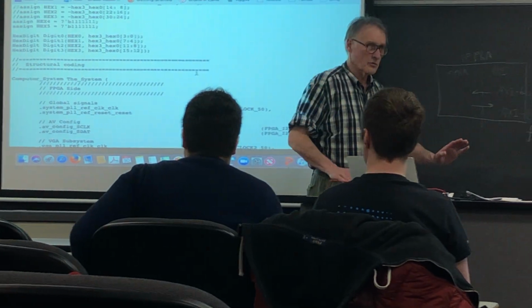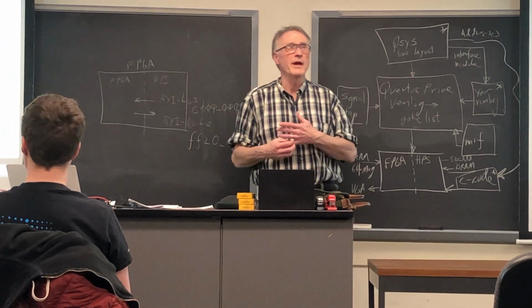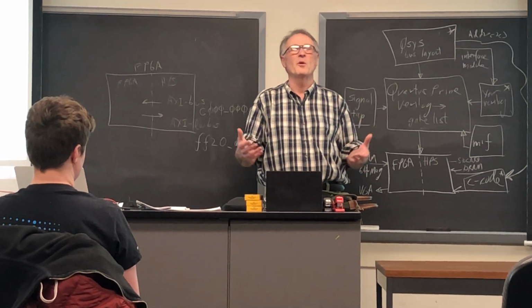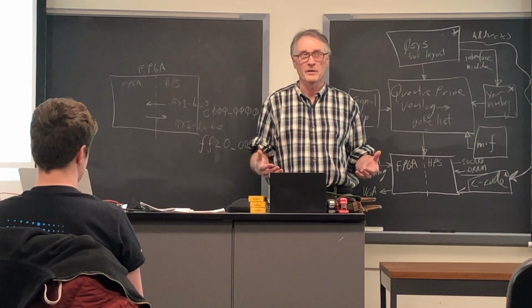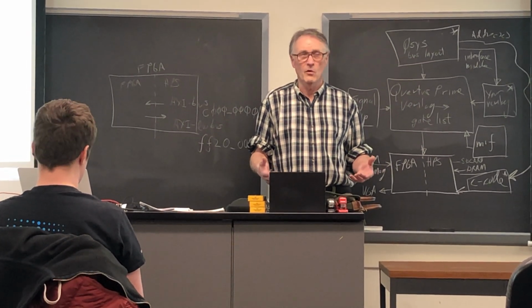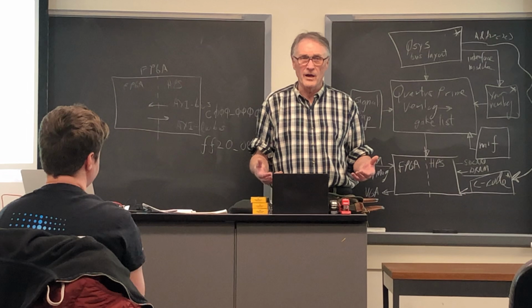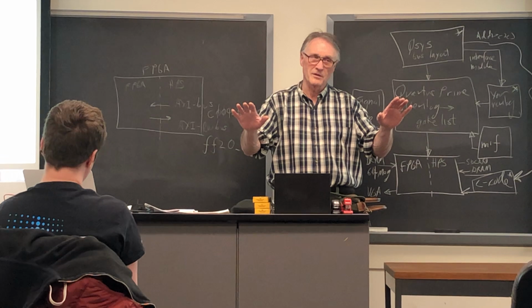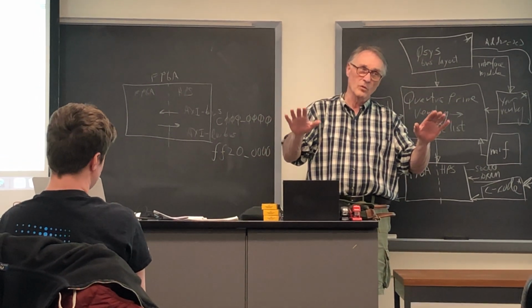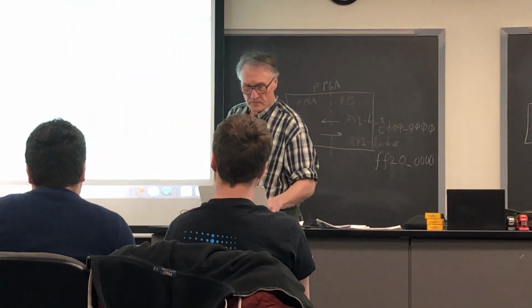You find that module in a subdirectory. There's going to be some directory where you have unzipped the file and you do the Qsys compile, and there'll be a subdirectory, a subfolder off of that called something like synthesis or the system or computer system, and in there will be a .v file, which is this interface file. It's not the whole disaster. It's not the million lines of Verilog that's generated to generate the Qsys. It is only the interface, the exported signals.